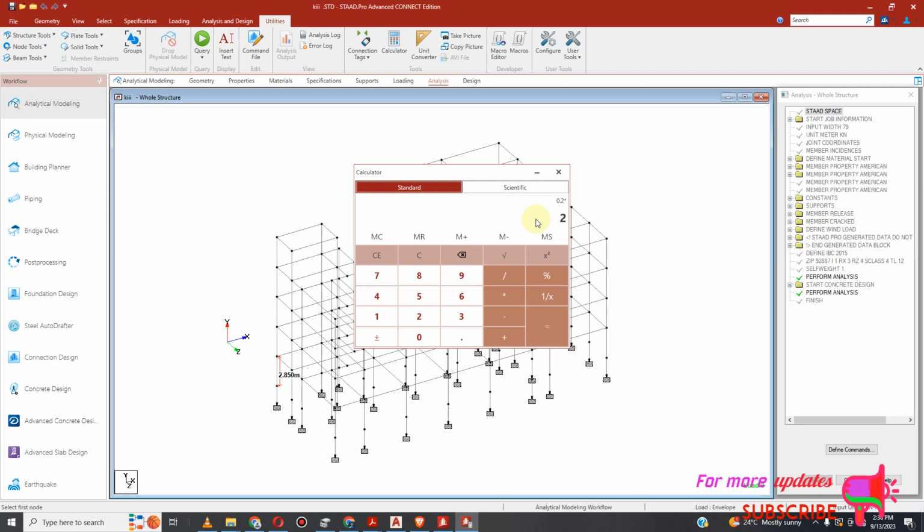That is the story height, 2.4, and then multiplied by my characteristic unit weight of masonry. So I will use 20. So equals, my wall is 9.6. That is my external and internal wall.